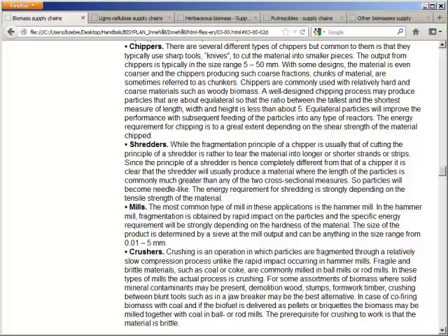Reasonably wet or moist biomass can well be chipped, whereas, for example, dry wood is very difficult to chip because it has a very strong resistance to the cutting operation, whereas moist wood, such as 30% moisture content, is easy to chip with a low energy requirement.